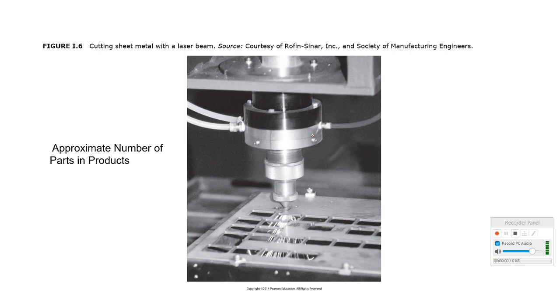This is a laser cutting that we have seen. So we can do precise cutting. Depending, either we can use blanking in order to cut this, or we use laser cutting. So it depends on how many we want to produce, the accuracy, the time. For example, if we have a laser machine, we receive a smaller number of production. Let's say they want only 100 of these metals to be made. What is required is the blank which is left and the part which has fallen below. So are we going to make a die and mold in order to make the blanking? Or if we have a laser cutter, why not employ the laser cutter to cut it if the production quantity is not that high?